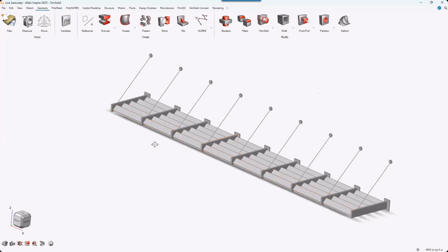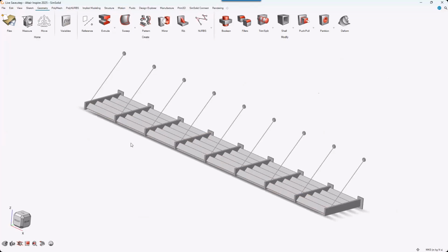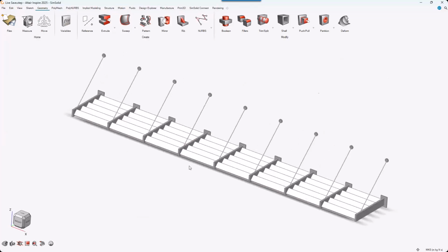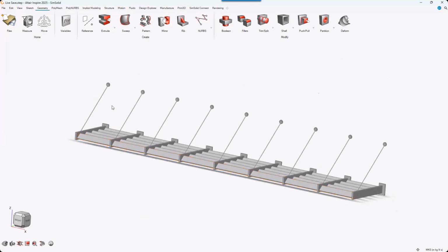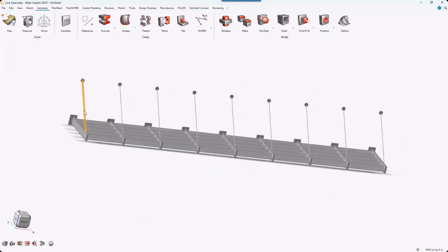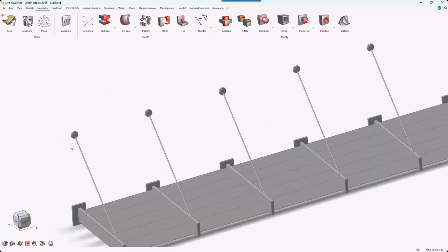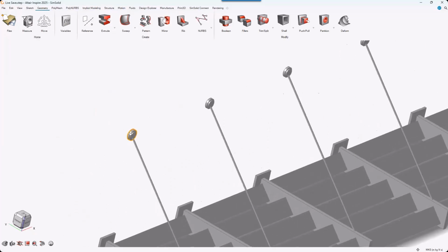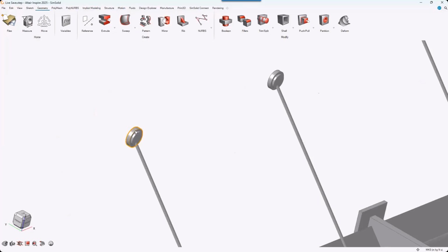If we were to import this into SimSolid, we wouldn't have all the editing tools directly, but we can actually run the SimSolid solver through Inspire directly. So here, I've got the geometry, and we'll be able to quickly identify some of the quirks that I showed earlier. For example, these louvers here basically extend through the entire set of these horizontals. I've also got some oddities related to some of these different brackets. So here I've got this circle with another circle inside of it.